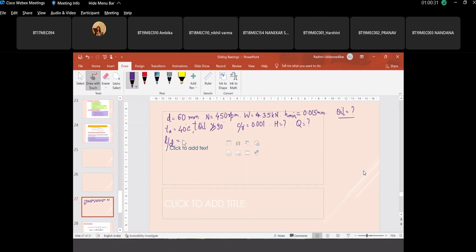Okay, let me make it a standard value. We'll usually by default go with 1.1 or 1.2. We normally have length a little more than its diameter. So let's go with L by D as 1.2. If D is known, you also know L, and if load is known, you also know the average pressure.